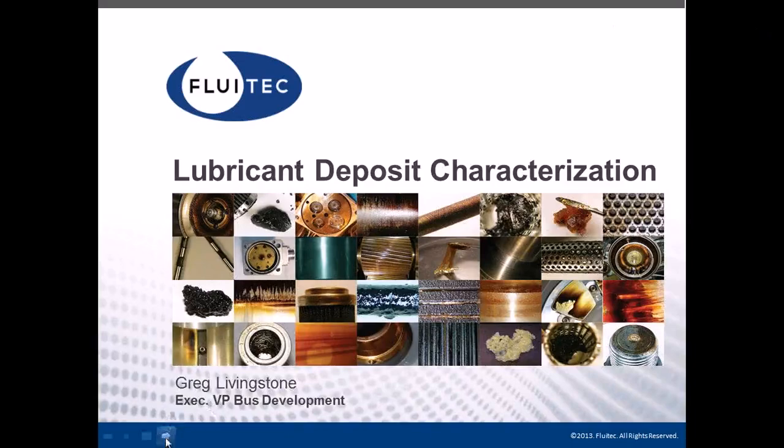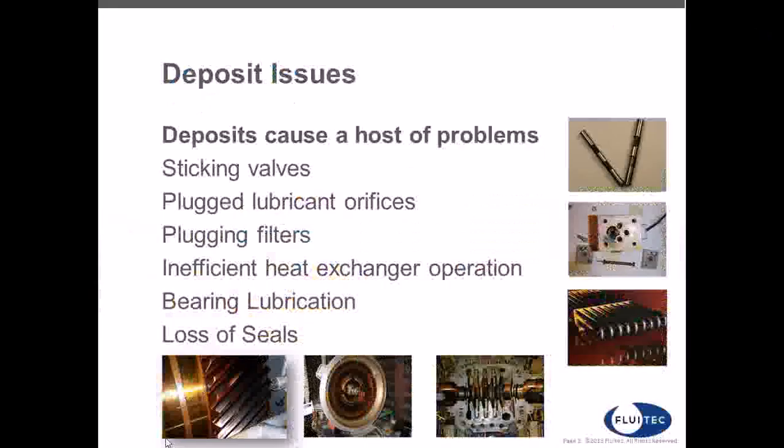Well, we know that lubricant deposits cause a whole host of different problems. Essentially, lubricant deposits are derived from various different stresses on oils that will degrade and change molecularly the components of the oil, so that these new degraded components are no longer stable in the oil, and they will come out of solution and form deposits.